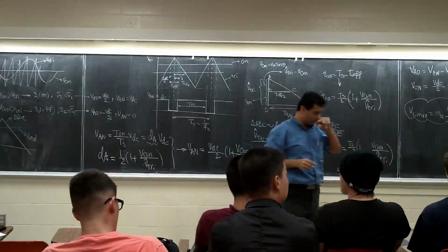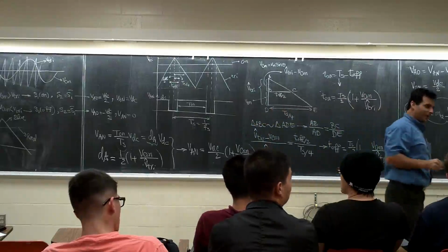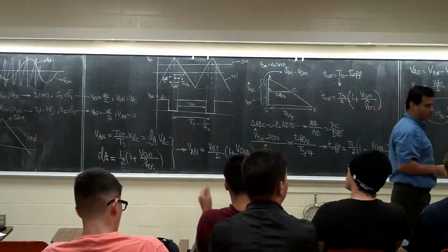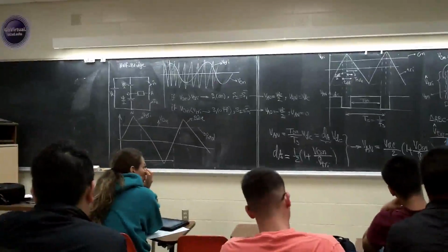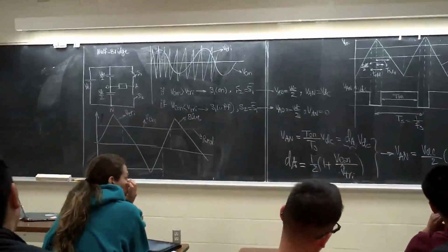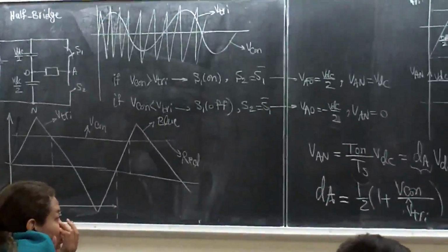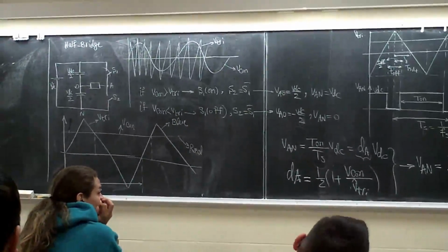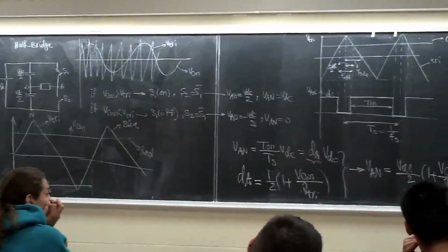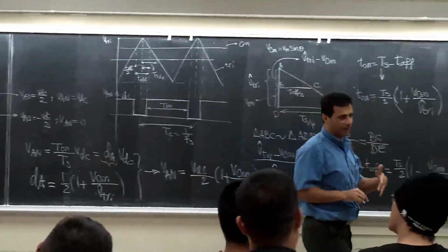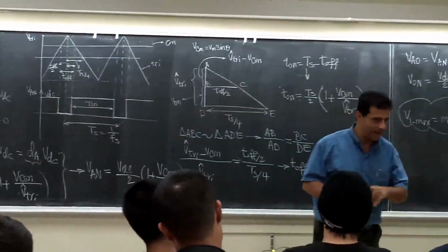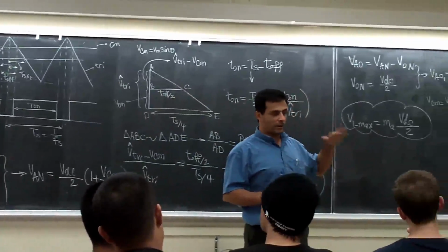But do you choose MA? MA is something you're going to work a lot with, that's the control parameter later. But if it's an open loop inverter, you have to choose MA. You choose MA whatever you want. But when it's a control loop, we limit MA to 1. We don't want to go more than 1 because we're going to get to the nonlinear modulation. That's when we get to the control part. We'll explain that. But MA could be any value between 0 and 1.